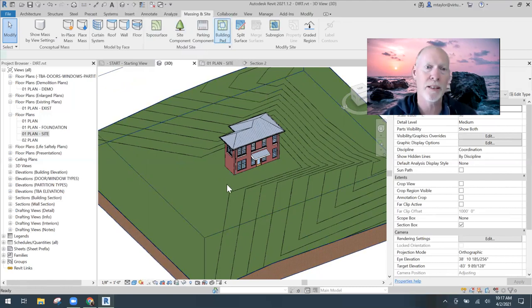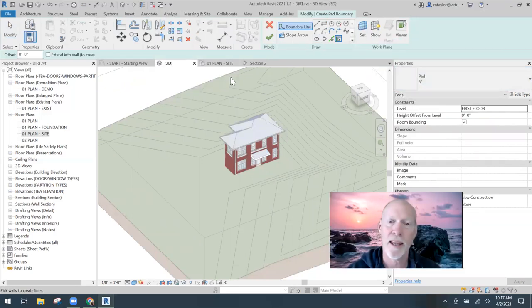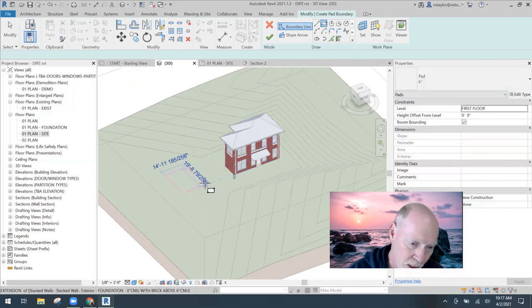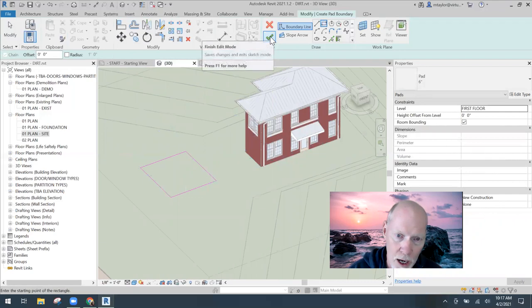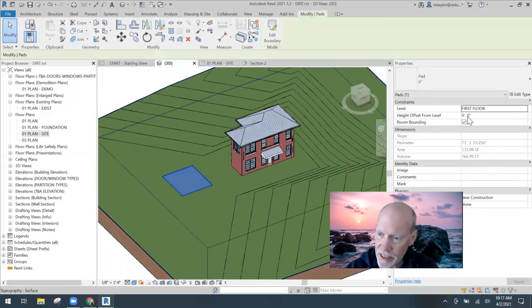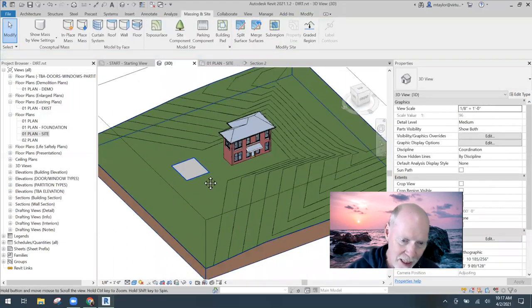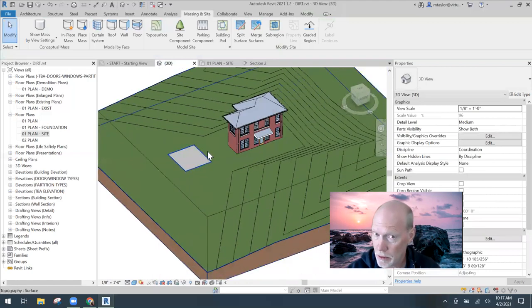So I can click on Building Pad, and if you look over, it's going to be a 6-inch pad. You can make multiple types of pads, but I want to show you. I'm just going to put a rectangle to make it easy for us. You guys see that? I just put a rectangle on the ground, and when I check the box, we have a pad, and when I highlight it, it says it's 0 inches off the first floor. So it's just sitting there on the surface, displacing the dirt, okay?